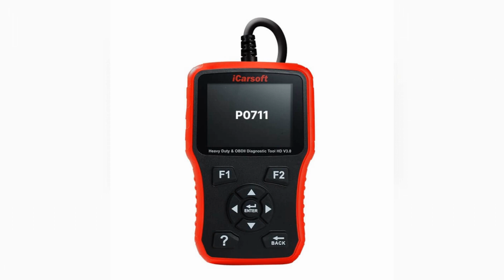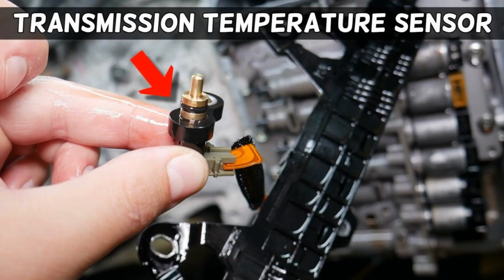Regular transmission maintenance. Schedule regular maintenance in accordance with the manufacturer's recommendations. This may include regular transmission fluid changes, replacement of the transmission filter, and thorough transmission system checks. Preventive maintenance helps prevent the buildup of residues and ensures optimum operation of all components.